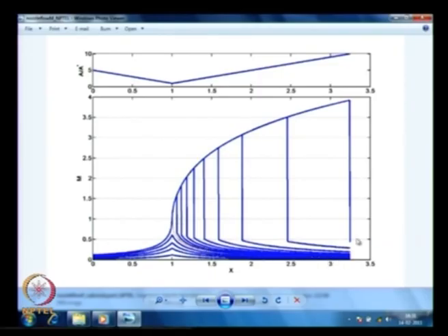If I decrease pressure further, it is going to go to even higher Mach number, and then from 3.5 let us pick, it is going to drop to 0.4 or so, it is dropping really high, while in the initial cases it is something of the order of 1.6 to 0.7 or so, rough numbers. Okay. It is jumping only a little bit, and when I go to the highest case I have, that is probably 3.9 dropping to 0.4 or so, something of that order. Okay. So it is dropping really huge amounts, which means the shock strength is high.